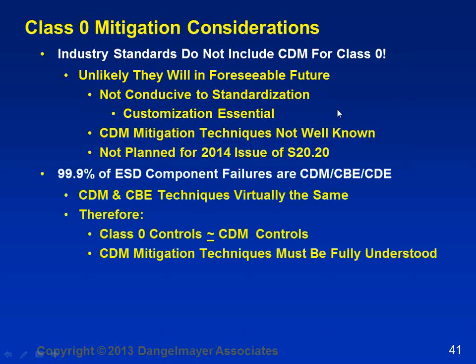And as we said earlier, 99% of the risk for device failure today is CDM, charged board, and cable discharge. Now, the good news is that once you understand CDM, the countermeasures for the charged board event are, in concept, the same.